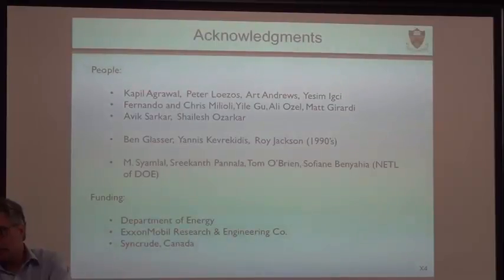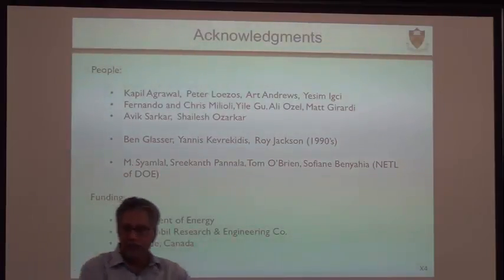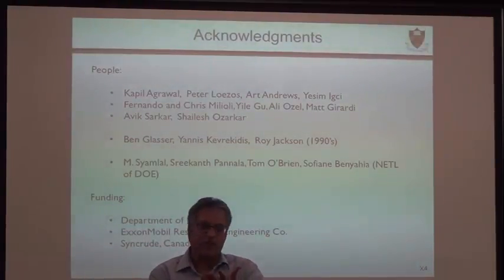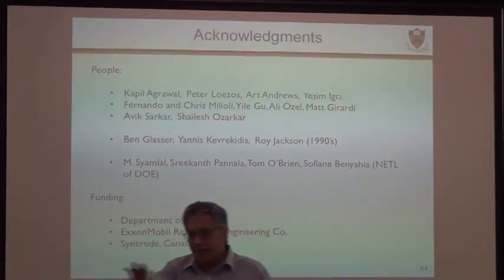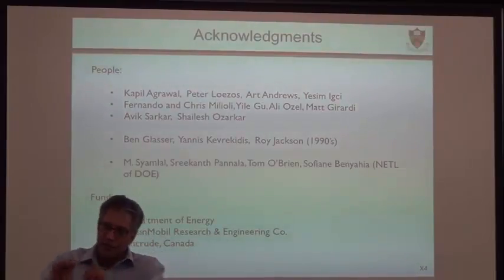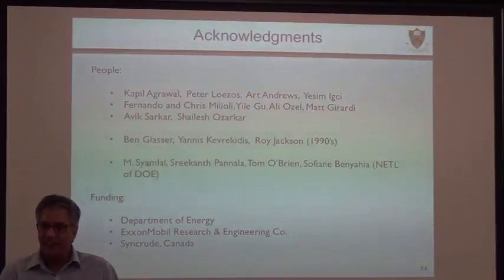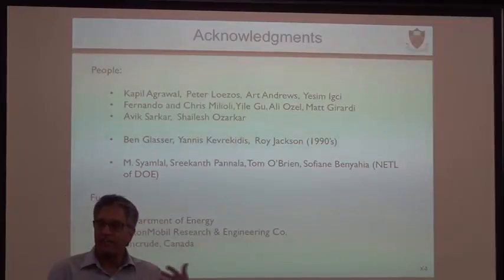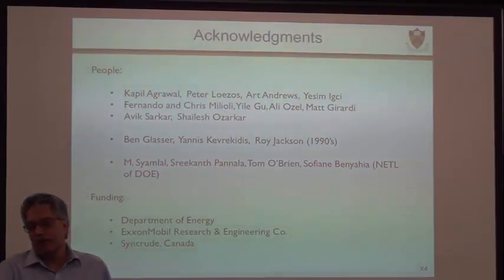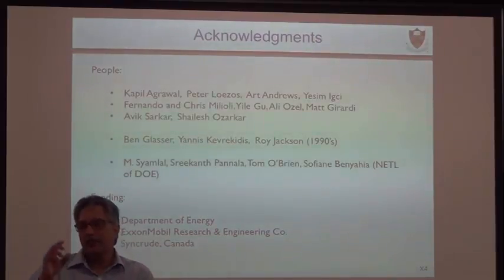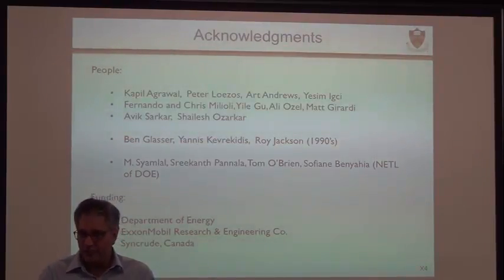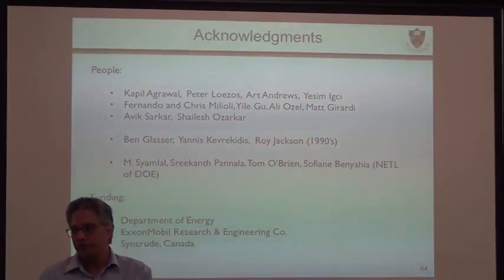So if you change the drag model, do you have to redo the scale? No, that's why we were talking about a fractional correction. That's why we talk about beta over beta micro, right? Exactly. If you change your beta micro, the fractional correction is still the same. We have tested that: if you decide that you don't like this drag model and use another drag model, and ask how to correct, my answer would be that the fractional correction is going to be very similar between different drag models.